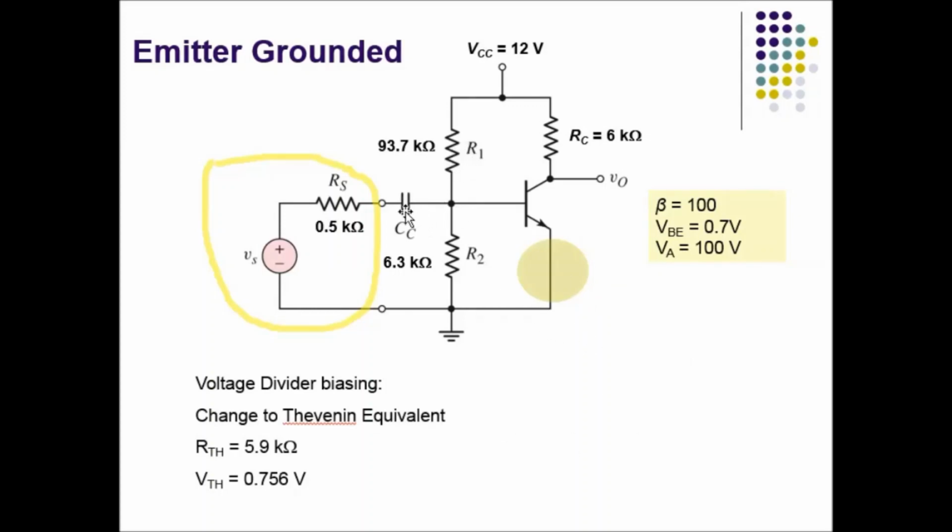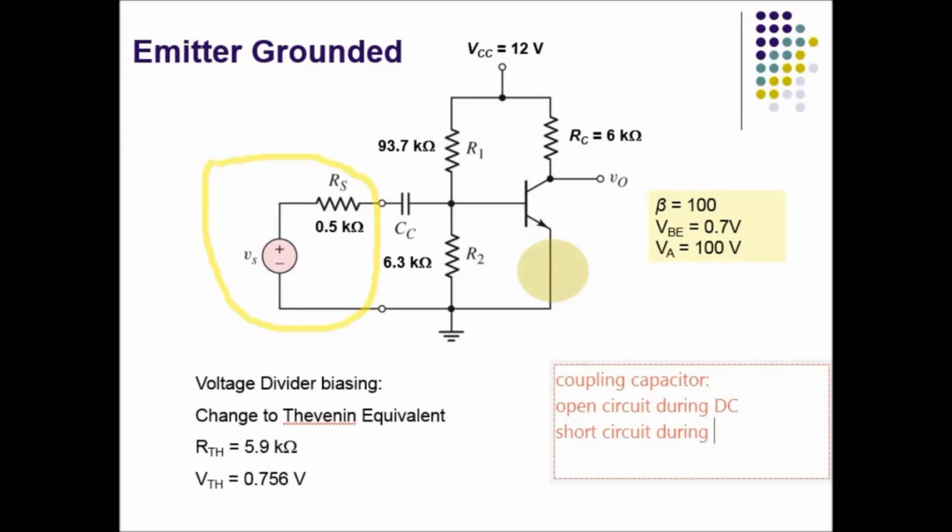However, during this analysis, your coupling capacitor will be open circuit. Because the property of a coupling capacitor is: open circuit during DC and short circuit during AC.